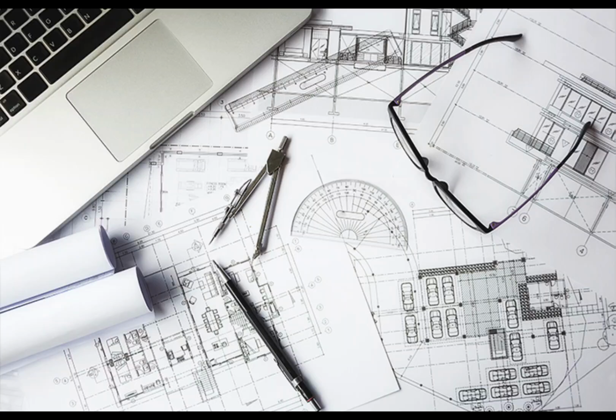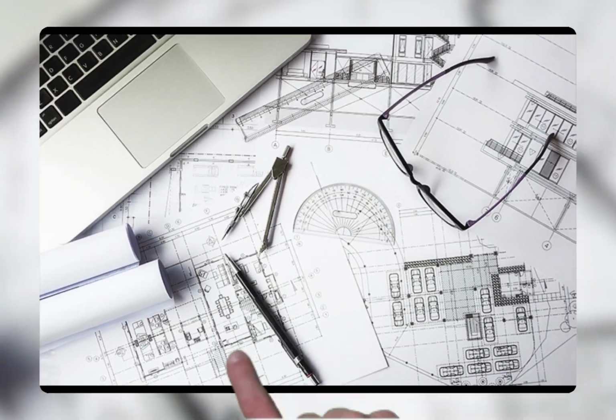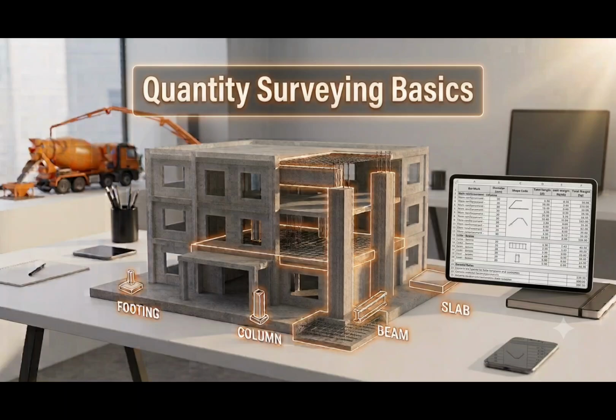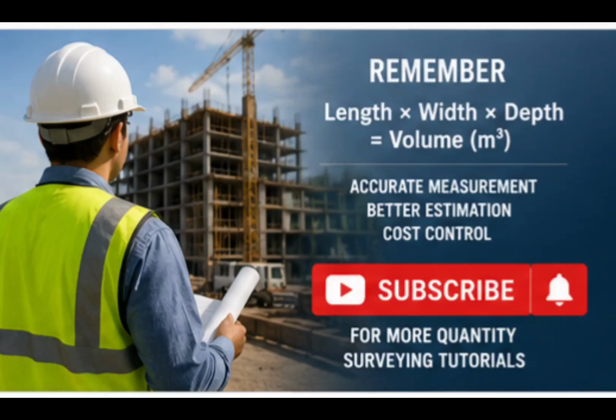Before we conclude, let's quickly review today's lesson. We learned the concrete quantity calculations for footings, columns, beams, slabs, and most importantly, we learned the basic formula: length times width times depth equals concrete volume. Once you understand this simple formula, you'll be able to calculate concrete quantities accurately for many types of structural elements.